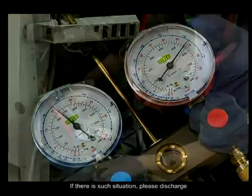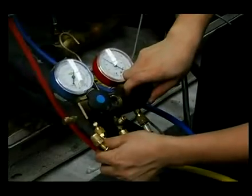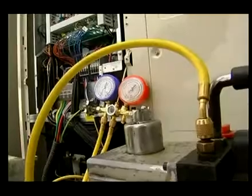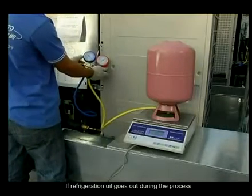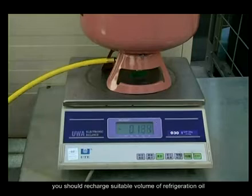If there is such situation, please discharge all the refrigerant of the system and vacuum again. Recharge the refrigerant after it has reached vacuum requirement. If refrigeration oil goes out during the process, you should recharge suitable volume of refrigeration oil.